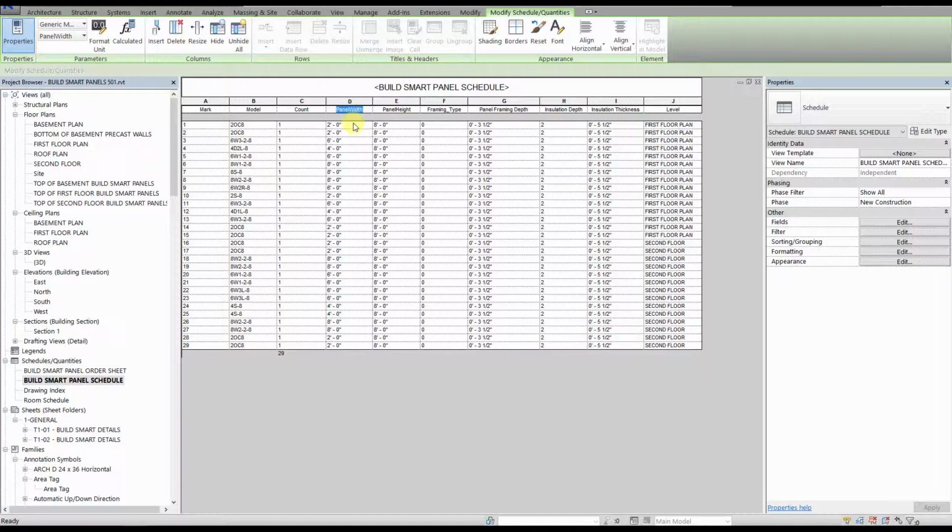If you do accidentally change a number, you will see either a 0 or a wrong mark in the model column. This will let you know that something got changed. Do not change the height of the panels using the schedule. If you change from an 8-foot to a 9-foot high panel by entering it into the panel height column, it will change the panel height and update the model number, but it will break the link between the family type name and the actual geometry of that element.